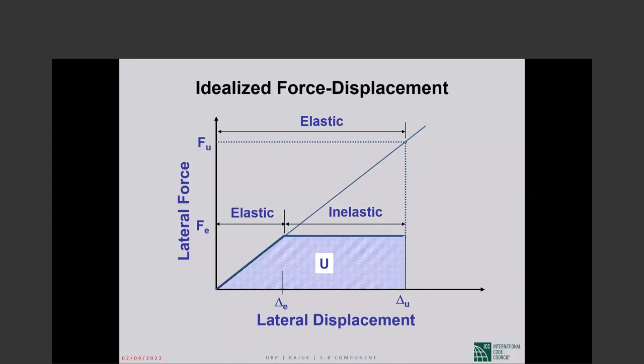You calculate a design base shear V, which depends on the R factor, which in turn depends on the structural system you're utilizing for seismic resistance. So that is one part. And depending upon the R value, you will also have to detail for inelastic deformation capacity that you need to go with the strength level you have chosen.